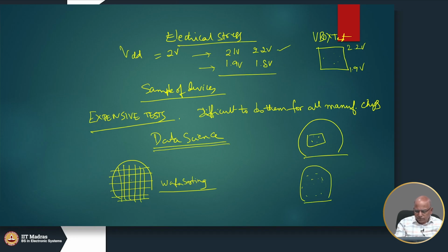After the wafer is manufactured, you will do what is called dicing. That means you will take a diamond cutter and cut all the silicon chips, and then the small chips will be packaged, and these are the ones which are sold. This costs a lot of money. This is called packaging and assembly.